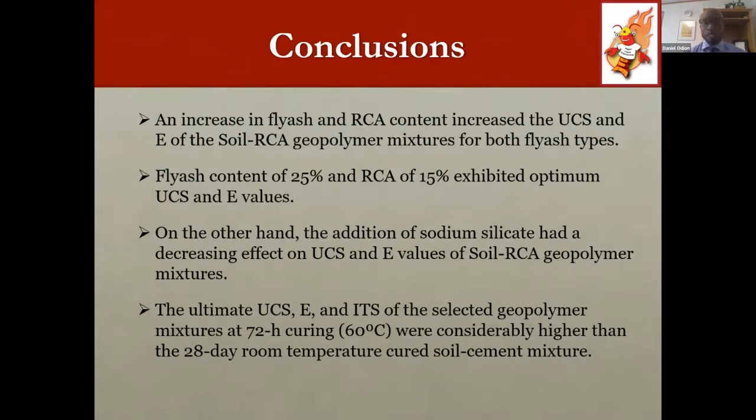Addition of sodium silicate, as I mentioned earlier, actually created a decreasing effect on the UCS and elastic modulus of the soil RCA geopolymers. Our temperature of 60 degrees was found to be actually higher than the 28-day room temperature for the pure cement. Let me also point out that we did a 45 degree, which is the kind of uniform temperature that we usually record in Louisiana, and we found that over time, this also yielded a higher strength than the 28-day room temperature for the soil cement.